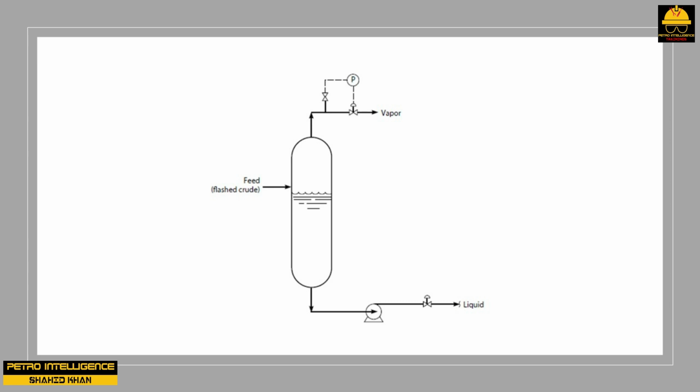It is true, as we said before, that raising the pressure in a drum does not increase the available NPSH, assuming that the vapor and liquid are at equilibrium. The idea of equilibrium assumes that the vapor is at its dew point and the liquid is at its bubble point. As soon as the drum pressure is raised, the vapor composition in the drum is altered. The vapor composition becomes lighter. The vapor, though, is still at its dew point.